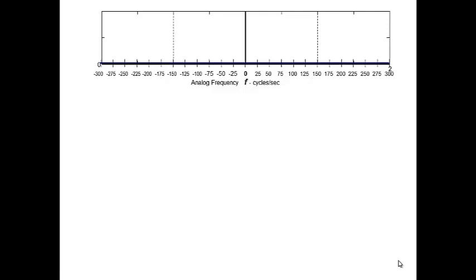Now when I change from a sine orientation to a cosine orientation, what do we do with the cosine? Subtract how much? Pi over 2, yeah. The cosine's 90 degrees ahead of the sine. So I'm going to have to take off a pi over 2 to make that substitution. So this is really a 4 cosine of 2 pi 100 t, minus 5 pi over 6. So 5 pi over 6 is our phase for a cosine, or minus 5 pi over 6. Okay.